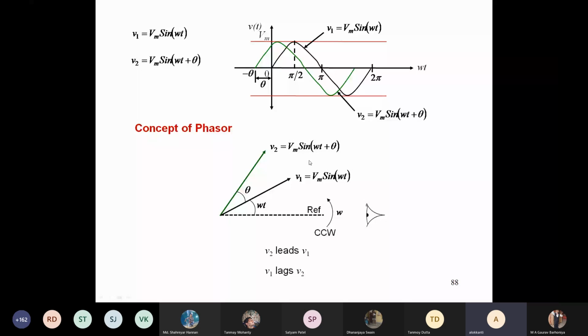So that is basically the concept of phasor. Whenever there is an AC quantity or alternating electrical quantity, it can be voltage, it can be current. They will be sinusoidal functions of time. Depending upon this theta, it will be determined, and obviously they have to be of the same frequency also, omega equal to 2 pi f. You cannot draw the phasors of multiple different frequencies on the same diagram. This is called the phasor diagram.